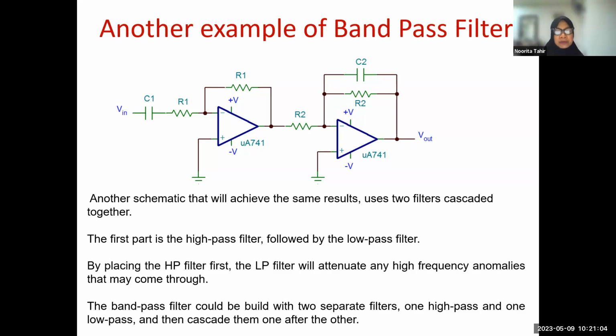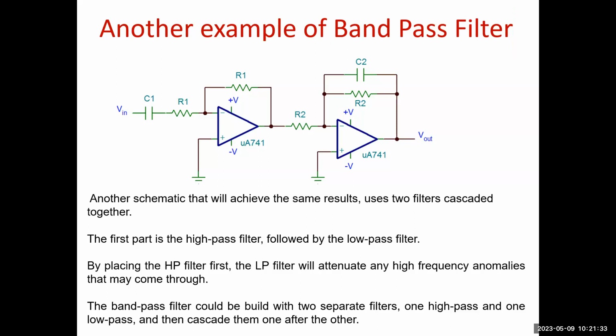I would like to suggest that you look into what the lower and upper cutoffs are, so we have some idea of the range of the bandwidth, because I am not sure as I haven't looked at your circuit yet. Maybe it needs to expand the bandwidth a bit. Can you try that?